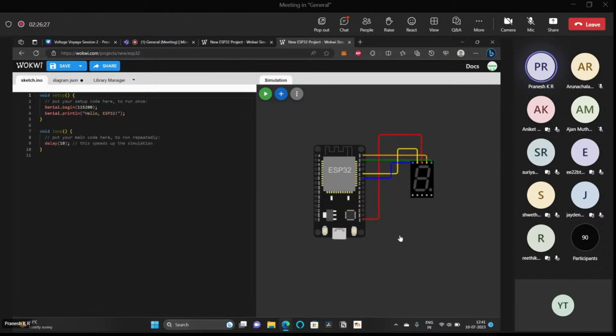It's not necessary to connect to these 4 digital pins. You can connect to any digital pin. Just make sure that you don't change the numbering. If you change the pin number, you change it in the code as well. If you guys are done with these 4 pins, do let me know. I'll proceed further.